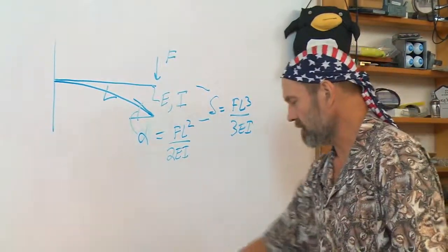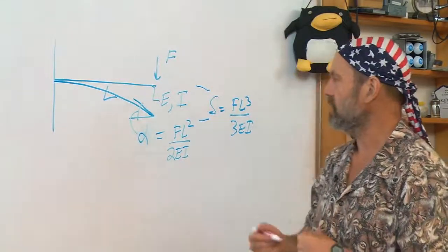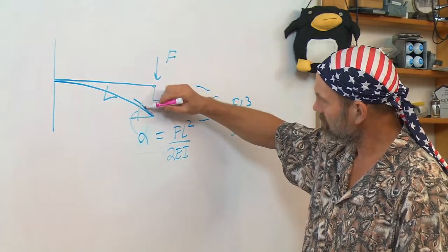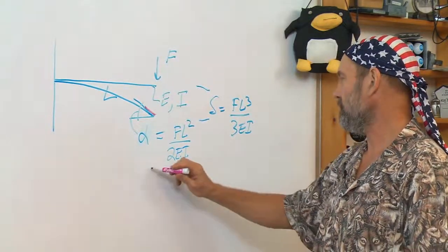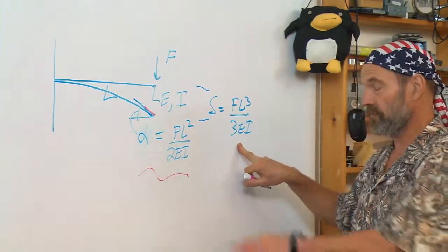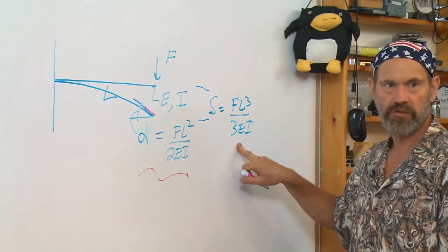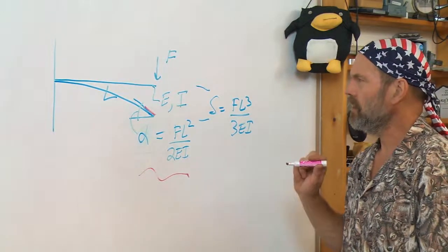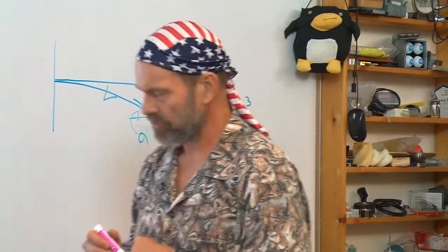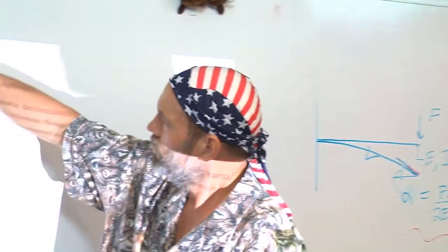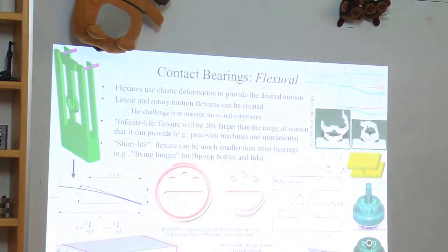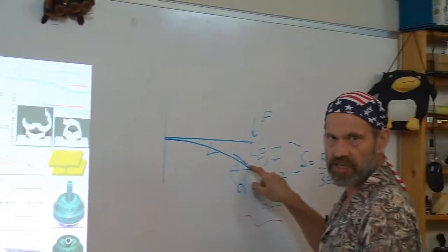So if you were to mount the lens element you're trying to create with pure rotation at the tip of the beam, you would get, for example, the slope you want, but you'd also get this deflection, which from the function required would be a parasitic motion. On the other hand, if, as the figure shows here, you have this arm reaching back, just attached to the tip of this beam.